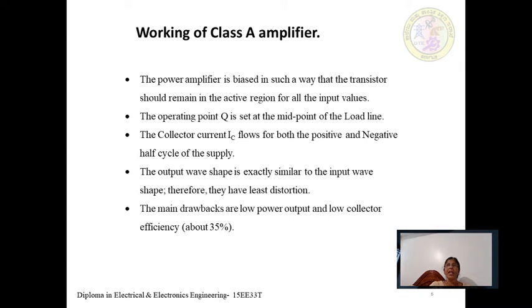That point is called the quiescent point, or it can also be called the operating point or the silent point. When the transistor keeps silent, the point where the transistor is silent is known as the silent point, or the quiescent point or the operating point. This happens at the zero signal values of IC and VCE, the point which meets the load line.